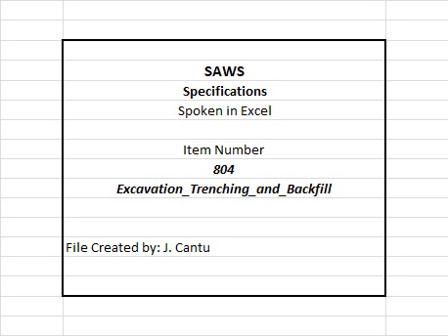804.6 Disposal of excavated materials. Any excess excavated material, not utilized after all fill requirements have been met, shall become the responsibility of the contractor. 1. The contractor shall dispose of it by hauling and wasting outside the limits of the rights of way or easements of this project and of public thoroughfares and watercourses, in conformity with pertinent city, county, state, and federal codes and ordinances and in a manner meeting the approval of the engineer or inspector.